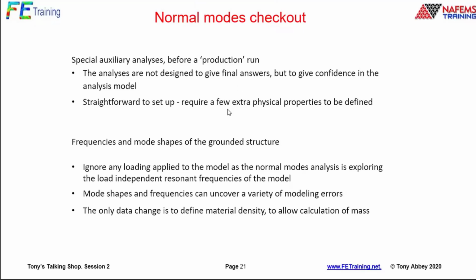We're going to see badly connected things in there. And I've come across a lot of people say, well, it's a normal modes analysis. That's dynamics. I don't have anything. I'm not a dynamicist. I don't know how to set these up. Well, every single user interface I've seen, as long as you've got the boundary conditions set up, that's the constraints to ground, you don't need the loading. You've got the right physical properties. You've got the mesh there. Just switch the analysis type to normal modes.